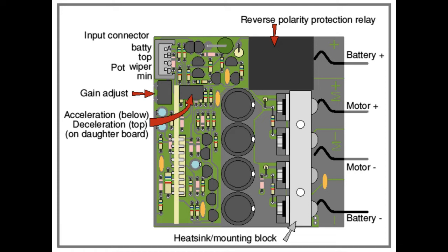The Uni 8 has a current limit that uses the voltage drop across its lower MOSFETs in the on state as a measure of motor current. This is okay at higher currents and has some advantages. For instance, if the MOSFETs start to get too hot, the voltage drop is greater and the current limit automatically comes in at a lower current. This approach was okay for the tender, and I set it initially to 30 amps, which is fine for my garden railway. It could always be raised later on test.